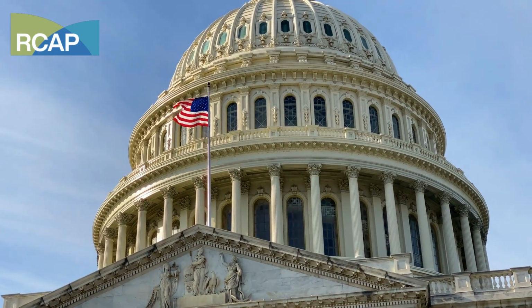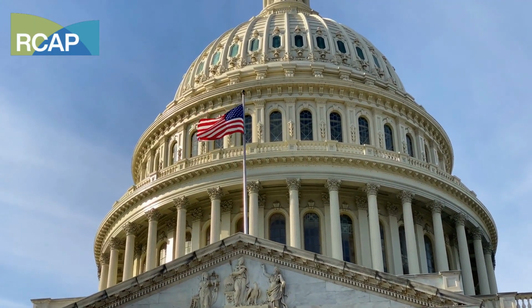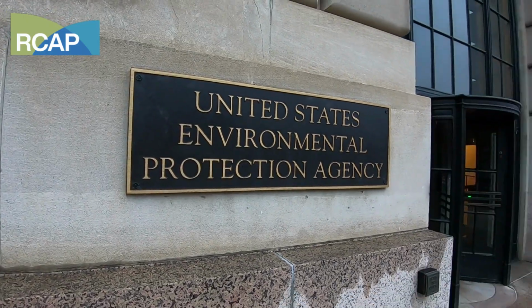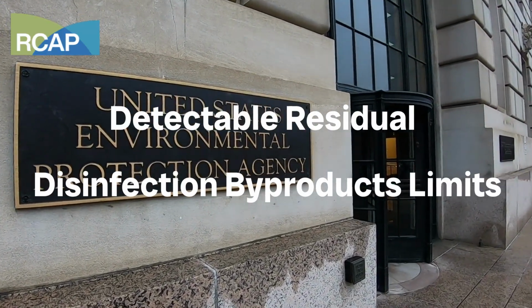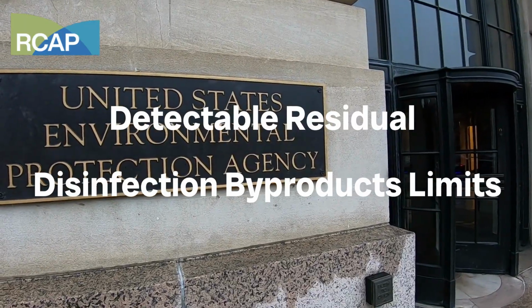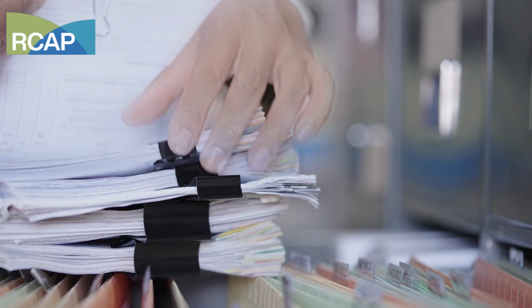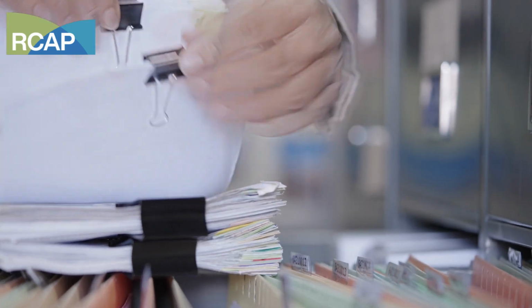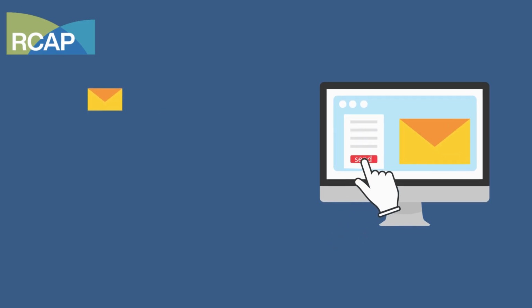There are federal regulations that could affect which type of disinfection process you choose. So let's look at a few of them. Federal regulations require most systems to maintain a detectable disinfectant residual in their distribution systems while meeting any limits set for disinfectant byproducts. Whether you use chlorine, chloramine, or UV, you must comply with EPA standards and keep detailed records of disinfectant residual levels. If your system doesn't maintain a residual or exceeds disinfection byproducts limits, that could be a violation. You'll need to take corrective action and may have to notify your customers.